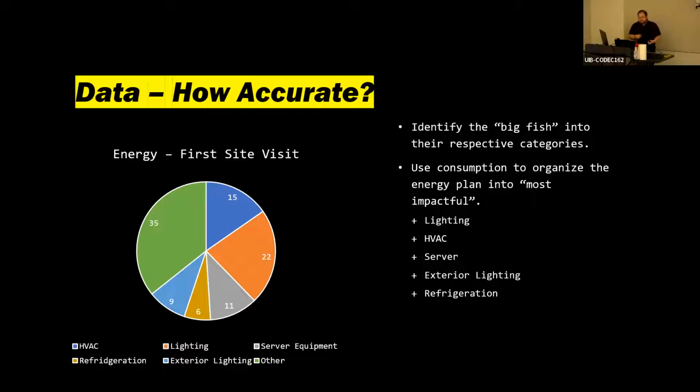So what that means is we're going to look at doing a lighting upgrade with a new fixture, possibly LED, looking at the control system, how many occupancy sensors or photo control sensors we potentially add to that. And again, looking at the HVAC, do we need to add more set points? Do we need to redo the zoning scheme and plan, or do you need to add, you know, a heat pump or a dedicated outdoor air system and revamp it, things of that nature.